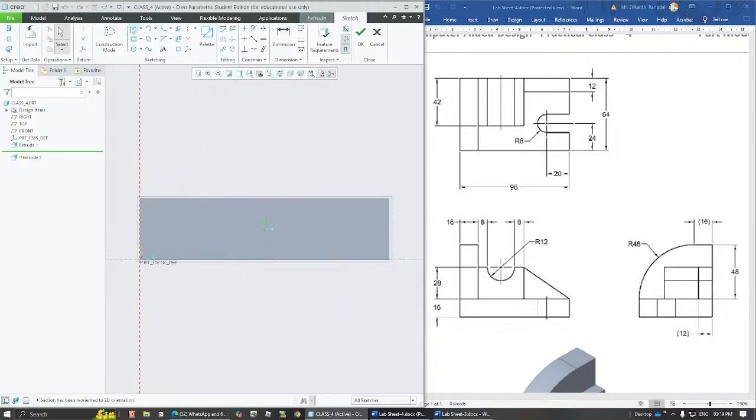I will need to draw it at this point, straight, a little straight, and then we have an arc which is coming and meeting here. So I'll take the 3-point arc, it's meeting here, maintaining tangency. Let me close this bottom one also.